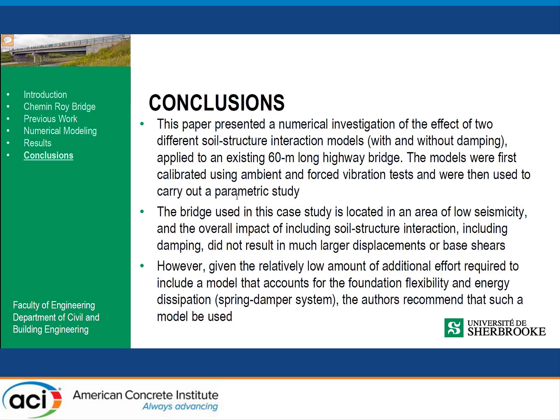However, given the relatively low amount of additional effort for this type of bridge to include a model including the spring and the damper system, we would recommend to use a model including damping and considering foundation flexibility and energy dissipation.